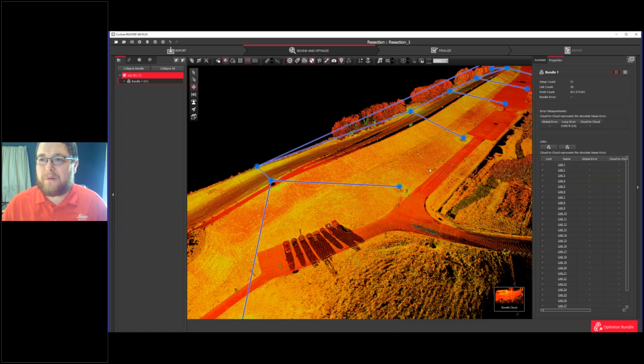One thing, and someone brought up a good point, and I don't think we've talked about this. Doing a setup backsite foresight method. Can we do that workflow in Register 360? If you do the backsite and foresight on the scanner screen, you're still going to bring it in as pre-registered, like this data set.